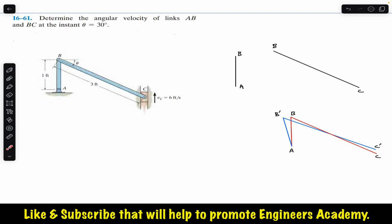And similarly, this point C moves in the upward direction and this point B moves in the downward direction. So link BC is in counterclockwise rotation as well. So the angular velocity of link BC is counterclockwise, that is omega BC. And similarly, the angular velocity of link AB is also counterclockwise.